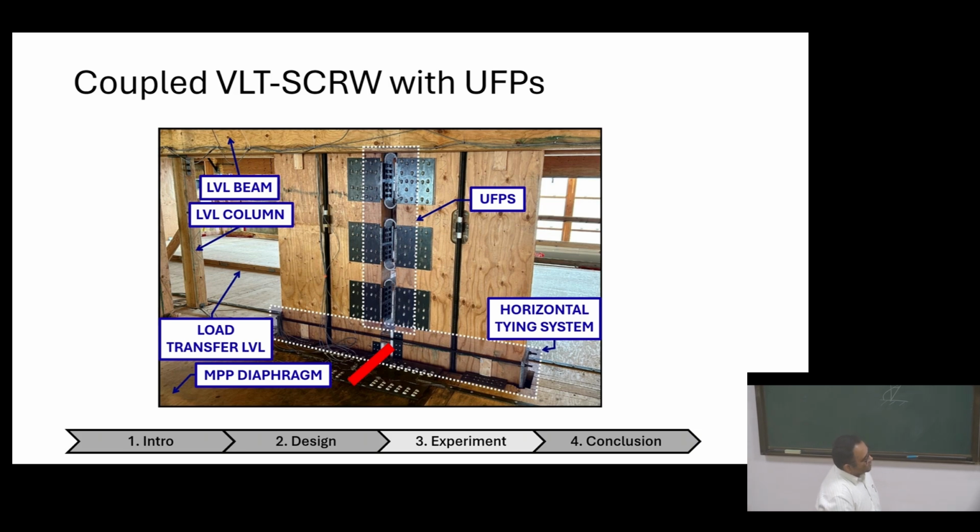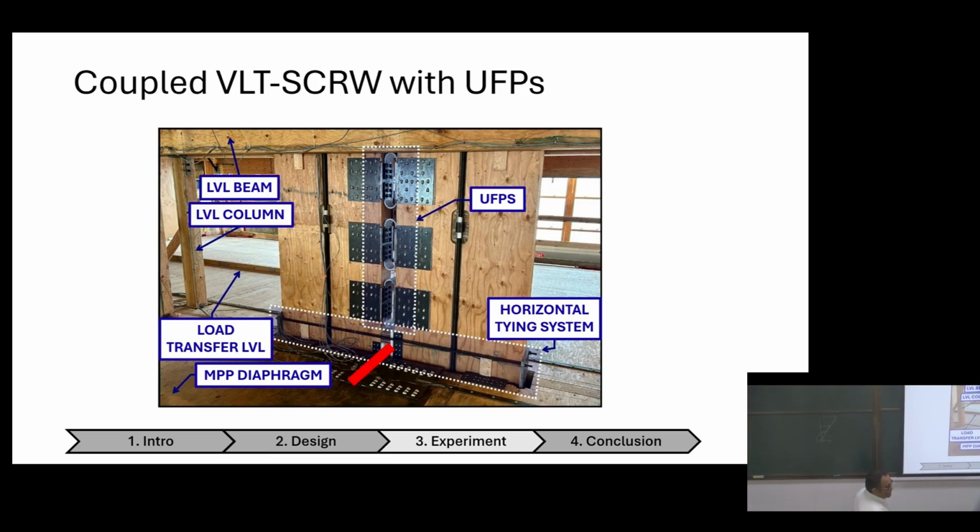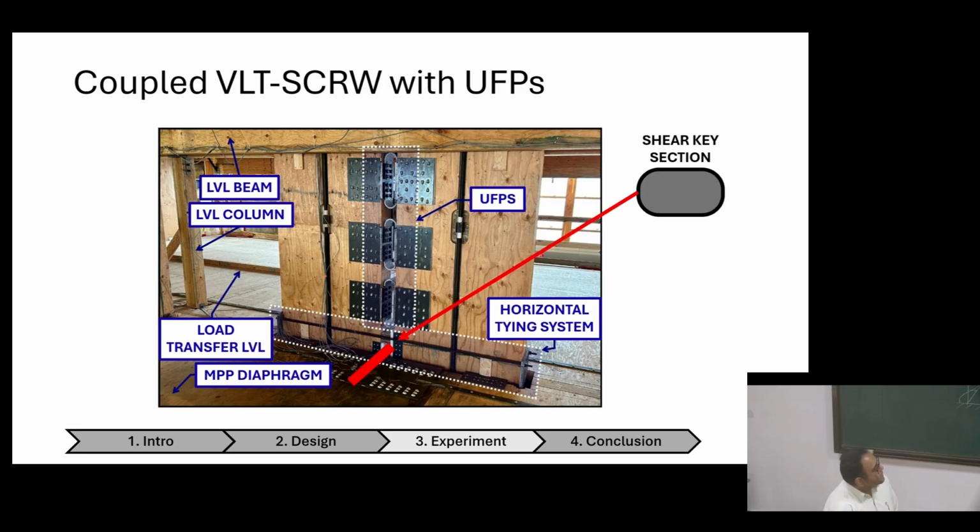This is the position of the bar. This is the position of the bar I was talking about, the steel bar that was welded to this plate. It's not very visible in the pictures, but it's welded here and welded on the other side. And that's stationary, and that bar transfers the load to the shear wall. And this is the shape of the bar.